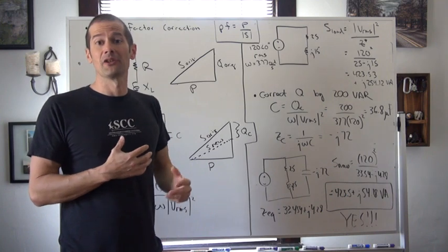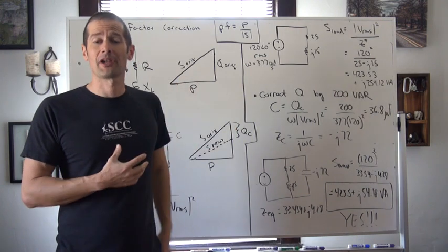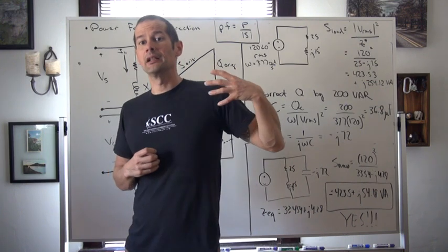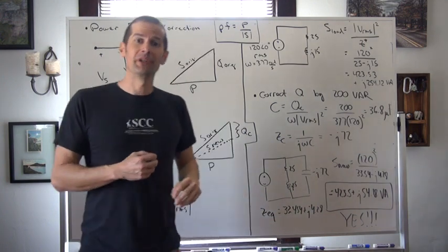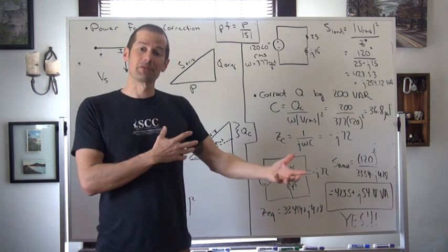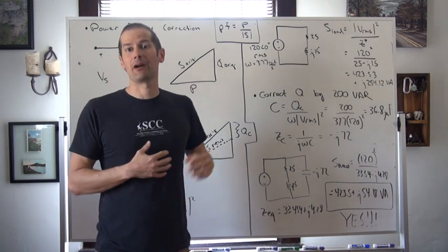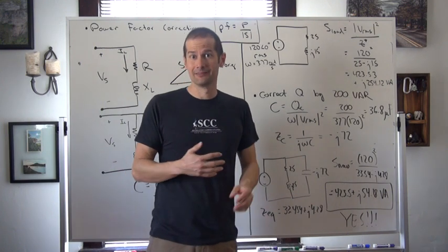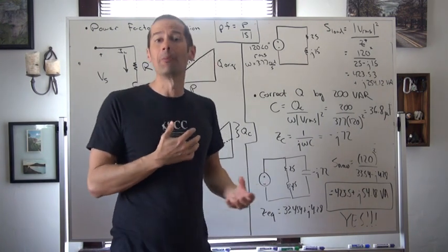So basically, as that ratio gets closer and closer to 1, we have mostly real power that's actually being delivered within our system. Now, sometimes with this idea of having reactive power in the system, and maybe even too much reactive power, by the law of conservation of power, we can introduce the opposite reactive power within the system by adding elements that bring that power factor closer and closer to a value of 1, or basically essentially 100% real power within that system.